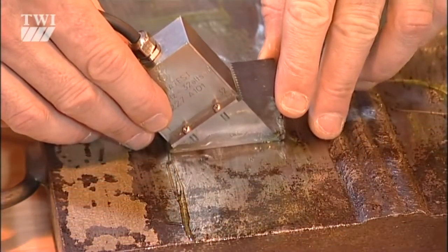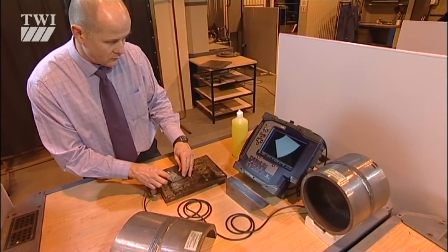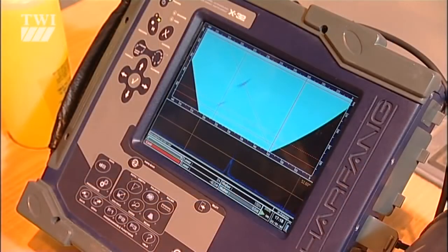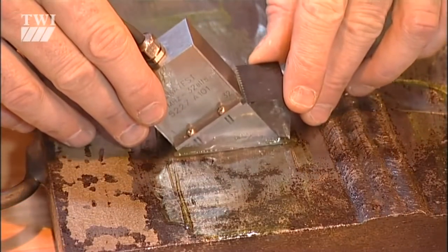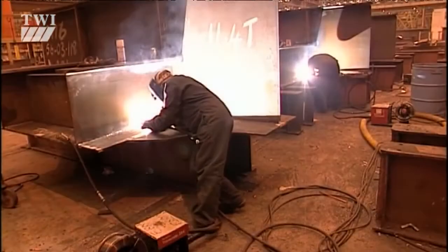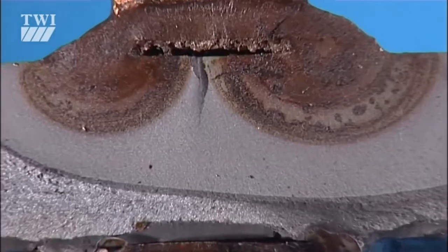Phased array systems work quite differently. They offer the possibility of performing inspections with ultrasonic beams of various angles and focal lengths, using a single array of transducers. So, what's it used for? Well, finding the same manufacturing flaws like lack of sidewall fusion, lack of root penetration, lack of root fusion, and porosity, in-service flaws like fatigue cracking,